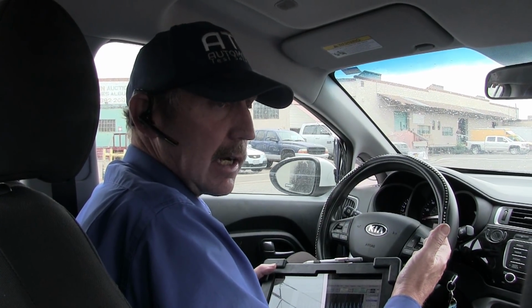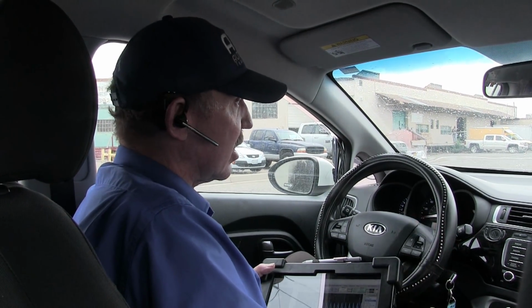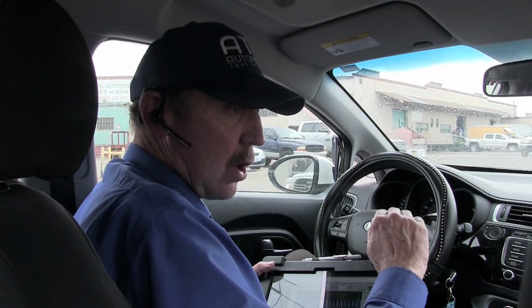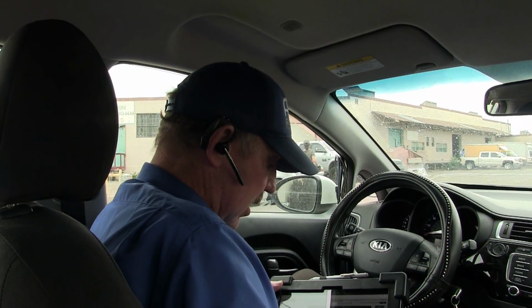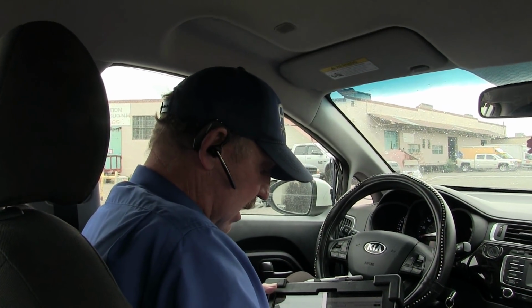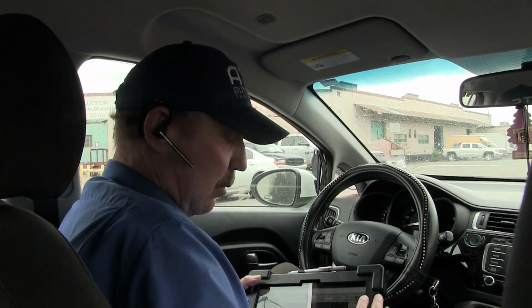The biggest problem is you can't tell what's happening with the scan tool. You couldn't even see that the wires were broken and grounding. You didn't see that till you got a scope on it. The scan tool just showed one nice curve that dropped. Till you put a scope on, you can't see all this other stuff. So I would have never known the wire was bad.